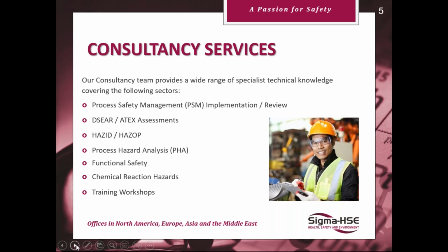We can help you with hazard identification and hazard operability studies. So someone can come on site and do a hazard study with you, and they can lead it or they can scribe. This is the best way to do it, to have someone in a hazard study who's not involved in the system on an everyday basis. Basically, the simple process is you can ask silly questions that someone who's involved with it all the time may not ask.